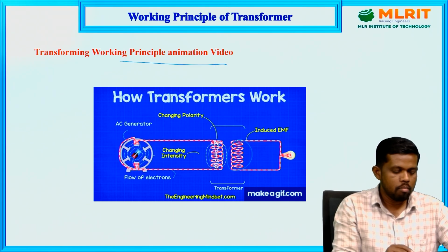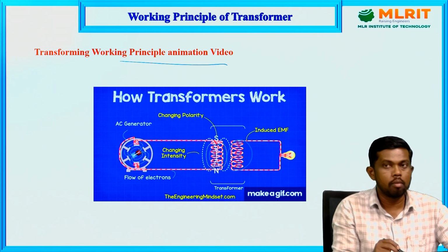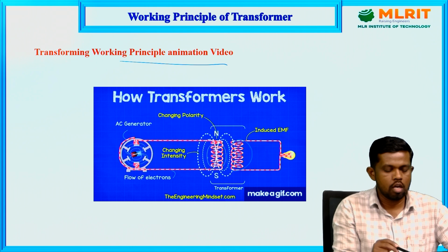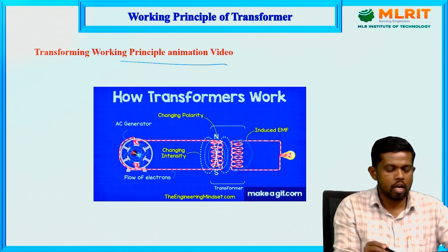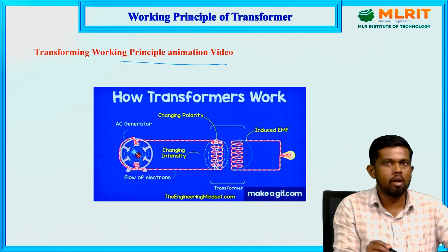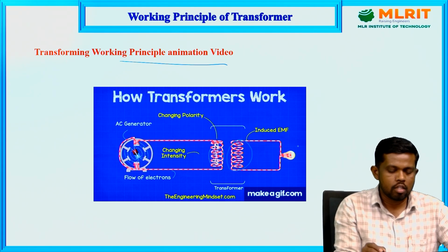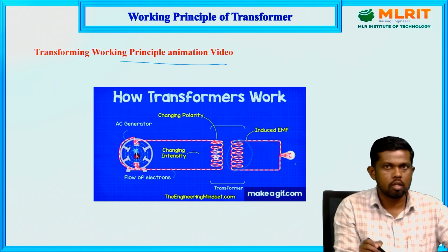The alternating source develops the alternating flux, which transfers the alternating flux to the entire transformer, and EMF is also generated in the transformer secondary winding because of mutual induction, or Faraday's law of electromagnetic induction, so that we get the bulb lighting up continuously.